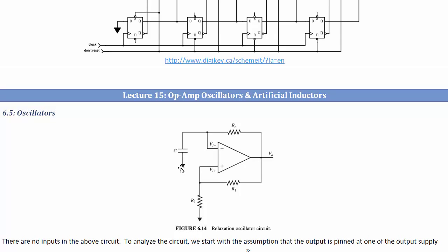Well, because this is grounded, on the discharging time, once this is 0 and we're sort of running the capacitor in the other direction, then we're going to have a really hard time getting the input voltage here to actually be lower than 0. So unlike before, it's not going to be able to get low enough. It's not really approaching a low enough number to switch.